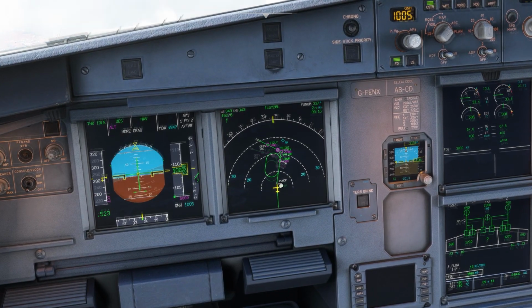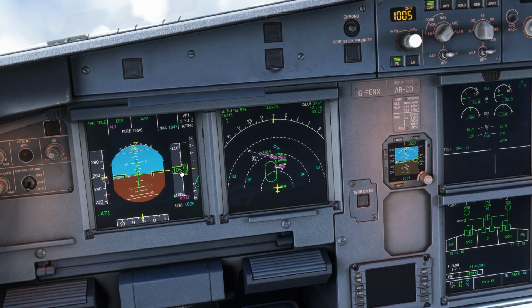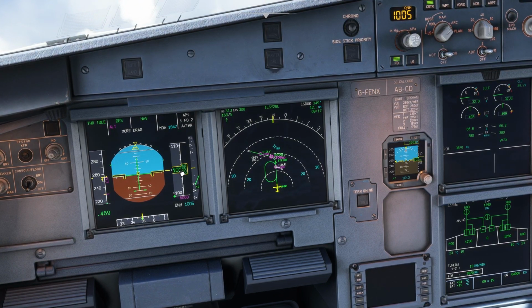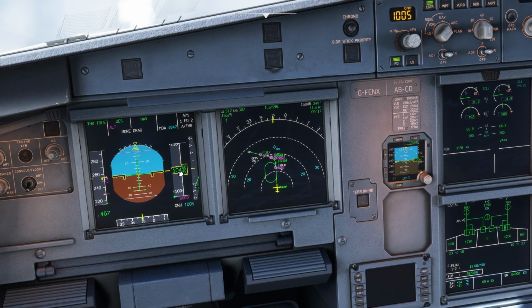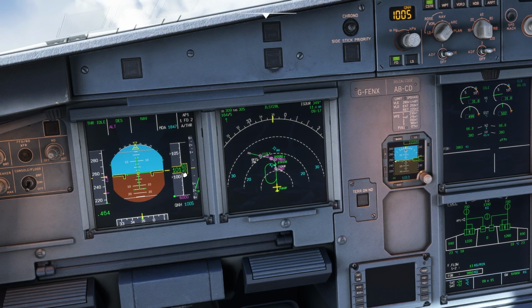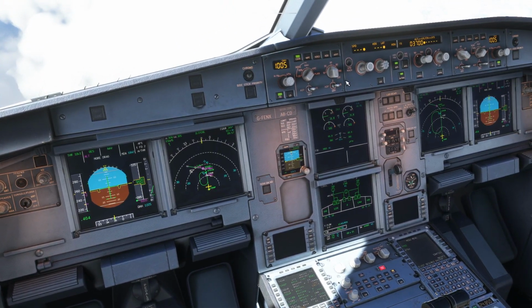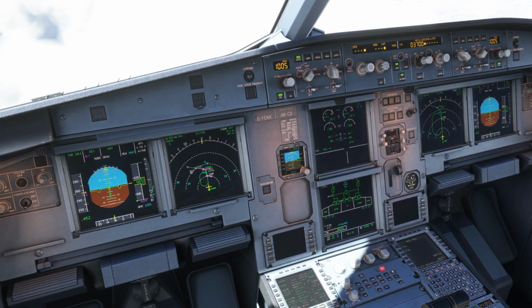As now the plane is going to reach 10,000 feet, and then will be going below 10,000 feet, that's why the speed had to be reduced. So as I told you before, till 10,000 feet the speed should be not more than 250 knots, and above 10,000 feet then you can increase the speed. So as now the plane is descending and it's crossing the 10,000 feet mark, that's why the speed is reducing. The autopilot has automatically reduced the speed. This is because of the managed mode. If you were going in selected mode, then you have to change the speed yourself.